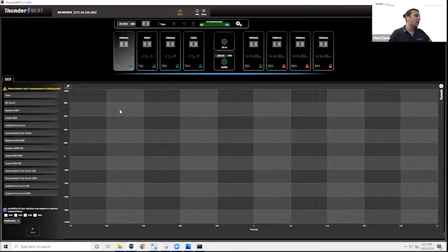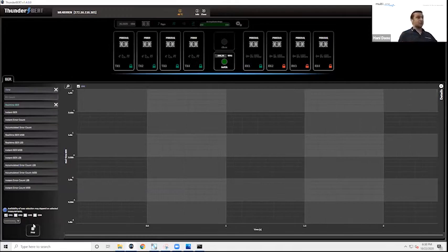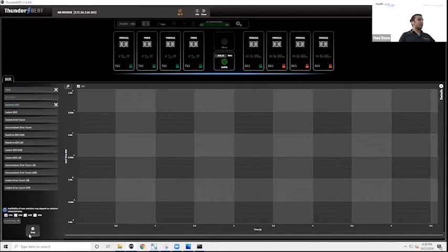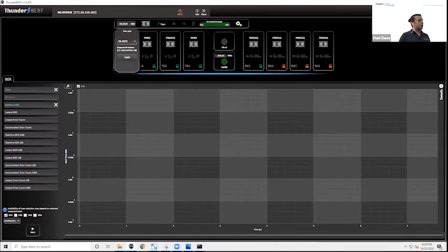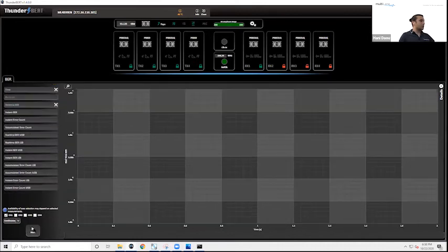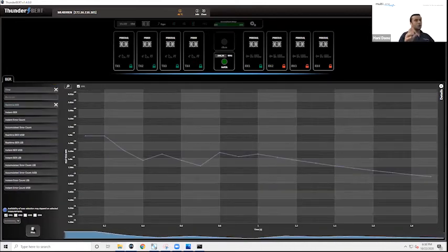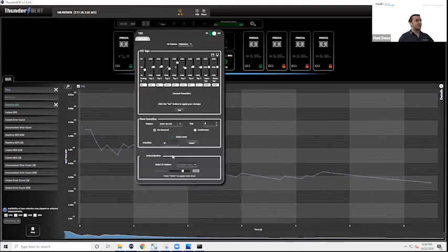Now, one last thing I want to show you is what that noise looks like on the error detector side. So I'm going to go ahead and do what I did before. I'm going to start a bit error rate test. We're at 26 gigabaud now. And you know what? I will go to 53.125 gigabaud just to drive the point home. Just like that, again, super fast. So I'm going to turn on channel 1, start my real-time BER test. And okay, according to my tap setting, I'm running at about 1E-10 BER.